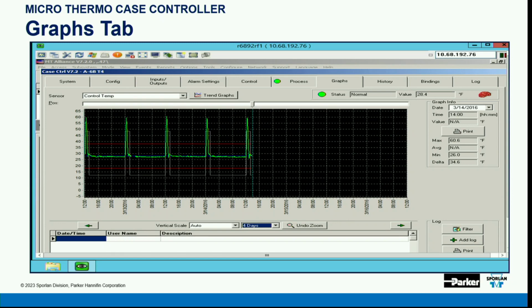But if we do a store properly, that's what your temperature control graph should look like. If you see it's all over the place, again, shame on you and me. We just didn't do our job properly. You should get flat line control. It should spike up in defrost. This is CO2, and when you come out of defrost, it drops like a rock.